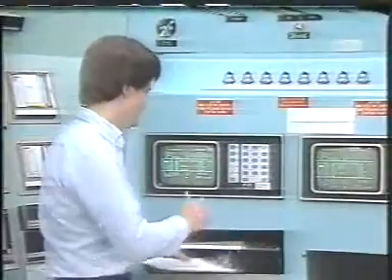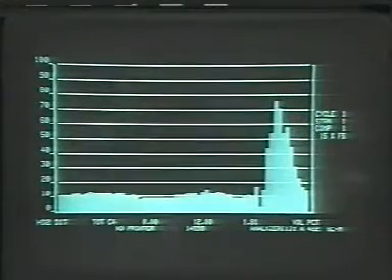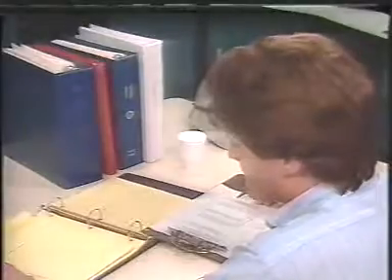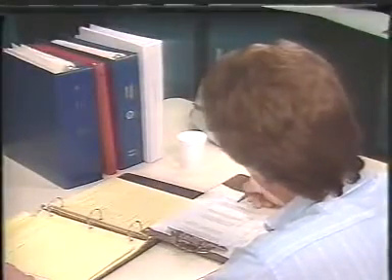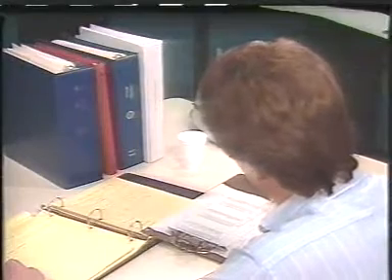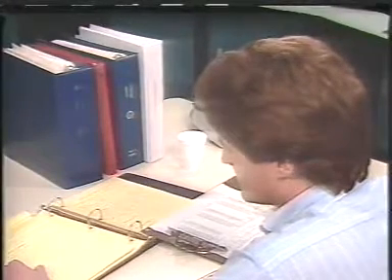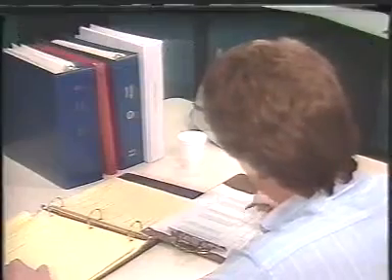On some distillation columns, process analyzers automatically monitor product specifications. These test results and instrument readings are recorded in the unit logbook and are then compared with previously logged instrument readings and test results. If the test results indicate a product is not meeting specifications or an operating variable has changed, it may be necessary to adjust the tower operation.